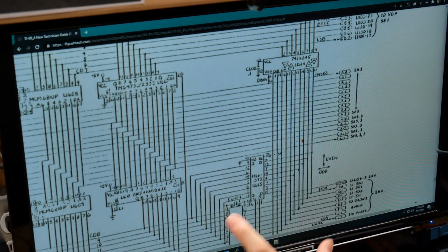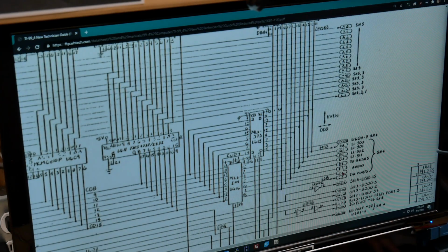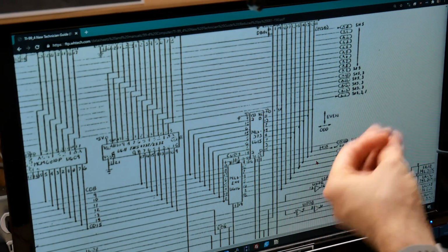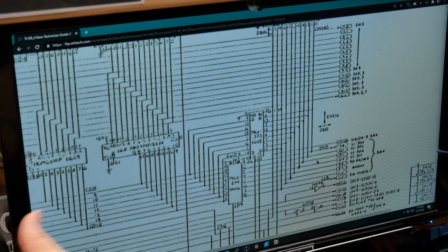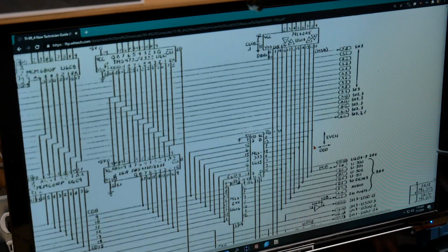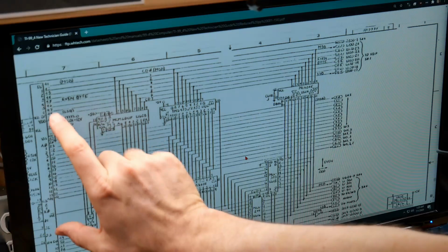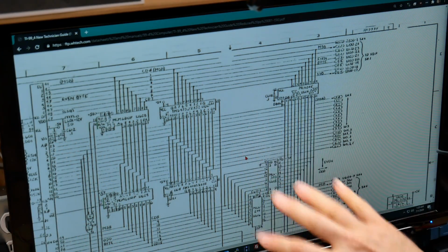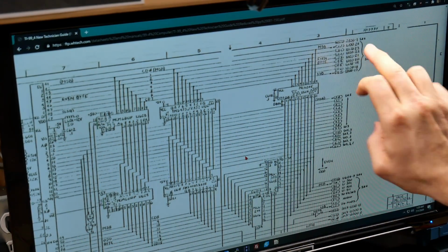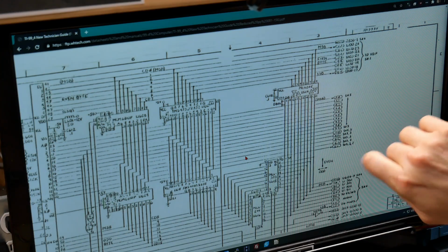And these 3 chips are what interconnect these 2 buses and allow things that are standard 8 bits to communicate with the 16-bit processor. This does absolutely confirm that on the 16-bit data bus, all that resides on that is the video display processor, which is going off here, off to a different page.